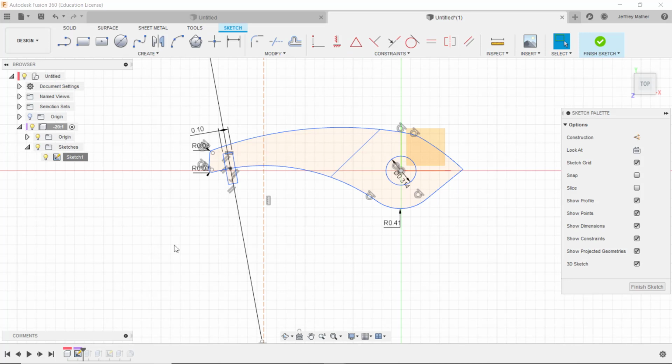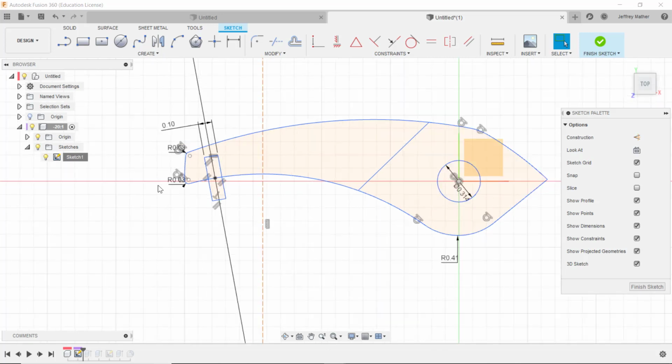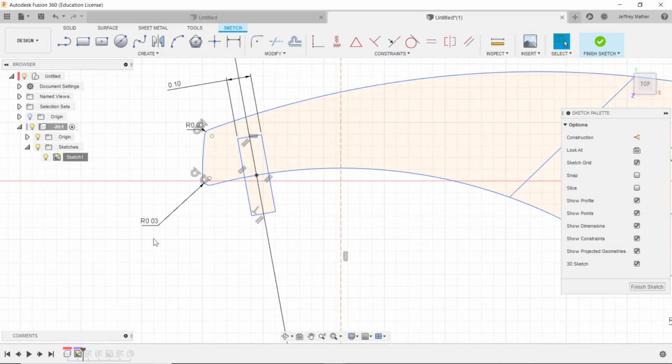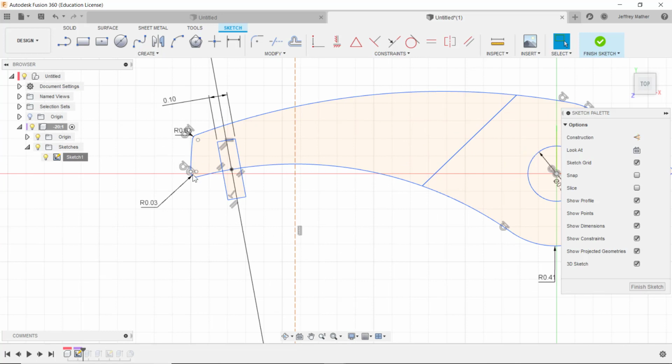So I'm going to edit this sketch, and I see that it only has a couple of dimensions on here. Every piece of geometry should be dimensioned with the dimensions that the person out on the shop floor would need in order to make that part. It's often best to put fillets, especially small fillets like this, in as features rather than as sketch elements.